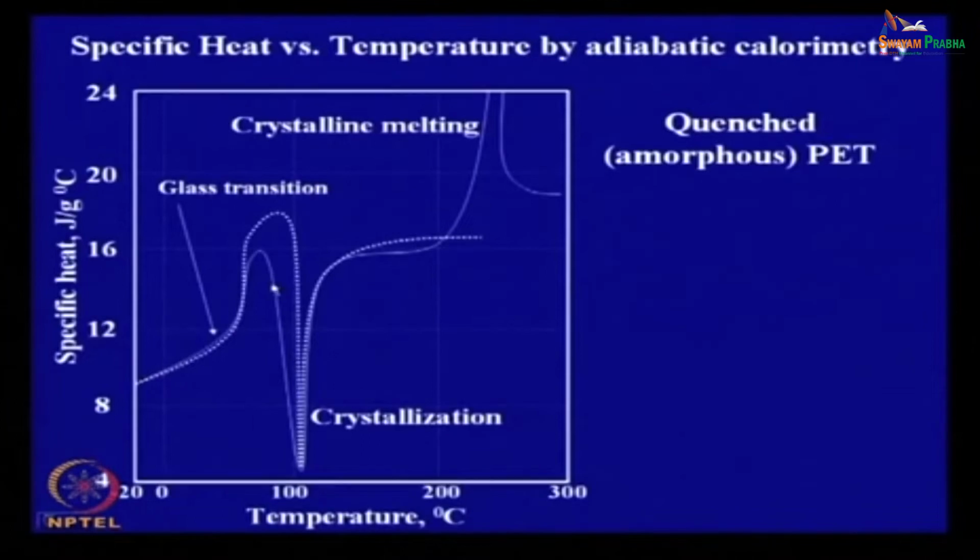This is another diagram which shows a change of specific heat values of polymers with the increase or decrease in temperature. You know what is specific heat of a substance. So, from that definition you can understand, and it shows a change in the slope of this curve, although it is not a sharp change. So, gradual change is there. In order to get the transition, you have to draw tangents at the 2 points, then the crossover point of the tangents gives you the glass transition temperature.